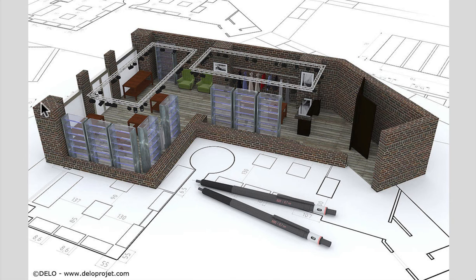You'll see in SketchUp, it's really easy to knock shapes away. So if you wanted to make that sort of exaggerated L shape, you wouldn't necessarily have to make the L. You'd just make a square and then extrude it, and then you would take another extrusion and just punch it in there, and it would delete it. So there's some neat techniques that you can use to expedite your modeling process.